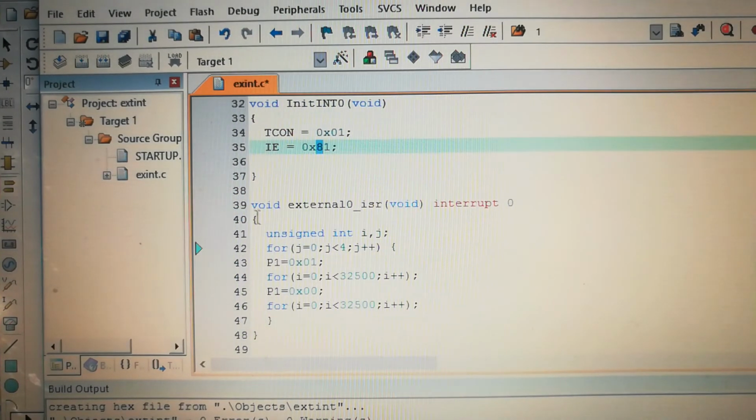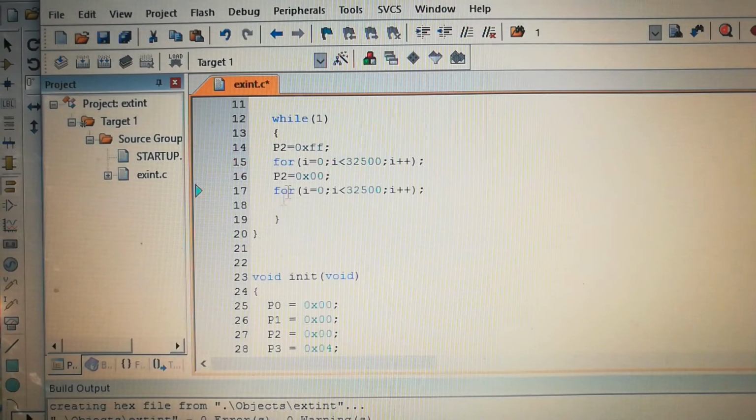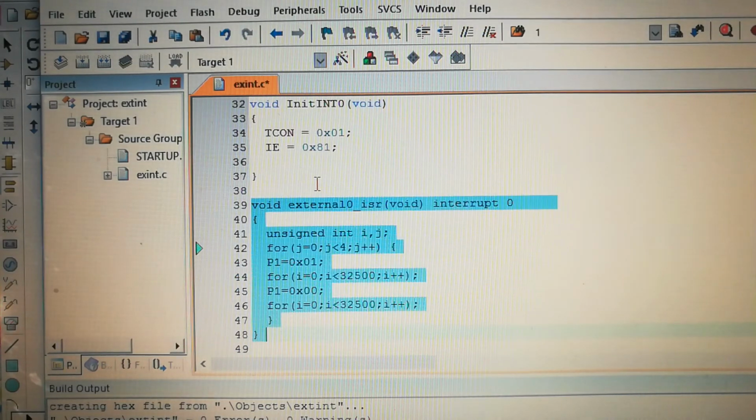And in this case, this is the interrupt service routine. Whenever that edge triggered interrupt occurs, it will jump to this method and serve it. After that, when it sees the RETI instruction, it will come out of this, go back to this while condition, take the top 2 bytes from the stack, and work on this case immediately.